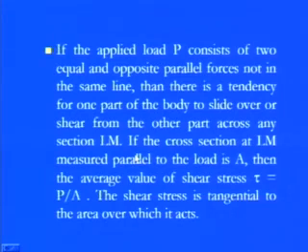Okay, so if the applied load P consists of two equal and opposite parallel forces, as we discussed in the previous case, not in the same line, because if they were in the same line, then definitely it would be an axial force, and due to these forces we would have normal stresses. But here, as we found, though they are parallel and opposite forces, they are not exactly on the same axis, so we have shear stresses.